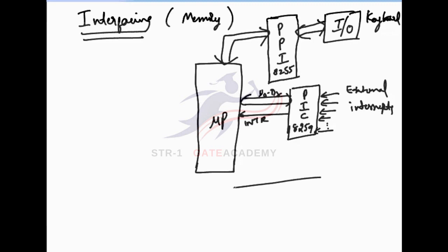So for interrupt controlling, a separate interfacing device, the 8259, is there. Similarly, sometimes we require serial communication. In the 8085 microprocessor, SID and SOD, serial input data and serial output data, are there directly. But sometimes we require different types of serial operation: simplex, half duplex, full duplex, synchronous and asynchronous. For that purpose, a separate interfacing device is used, called USART, Universal Synchronous Asynchronous Receiver Transmitter.